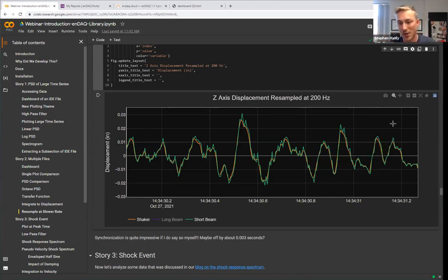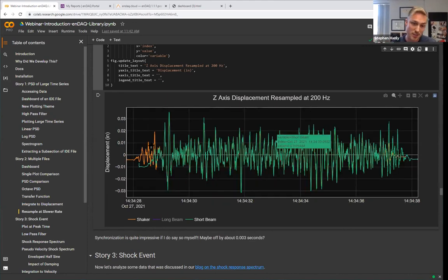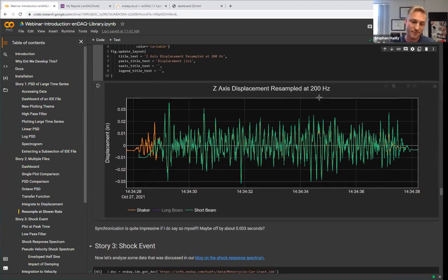And what I also want to call out is that this is remarkably synchronized. I didn't do any manipulation to the time data. I resampled it at a frequency, but I didn't shift the start times. So it's synchronized. And you see here the start times of these 2 recordings are off by about a second or 2 because I pressed the button on 2 of them like this, and then I only have 2 hands. So I pressed the 3rd device a second later. But just from the UTC time in our device, saving the calendar time, you have remarkably well synchronized data to within about 3 milliseconds, which I think is pretty cool.